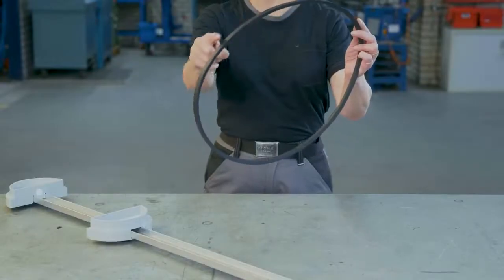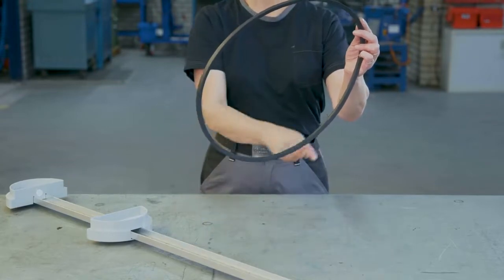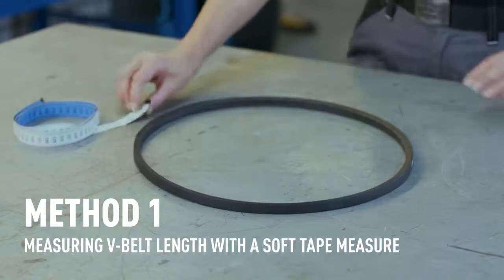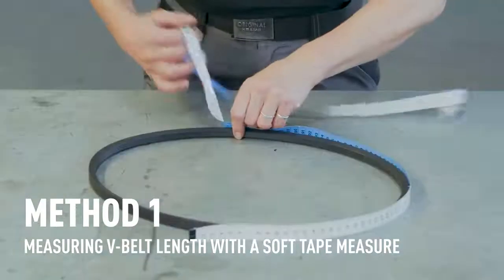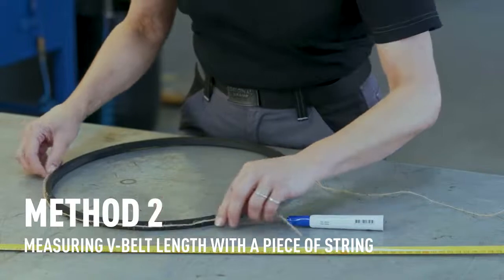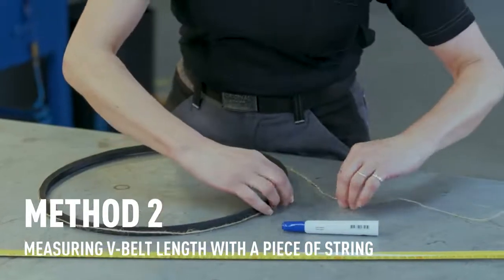The alternative is to first measure the outside circumference and then do the math and get the inside circumference to be able to determine the replacement belt you need. There are 3 ways to do this. Number 1, use a soft tape measure and wrap it around the outside circumference of the belt and take the measurement. Number 2, use a piece of string and wrap it around the outside of the belt.